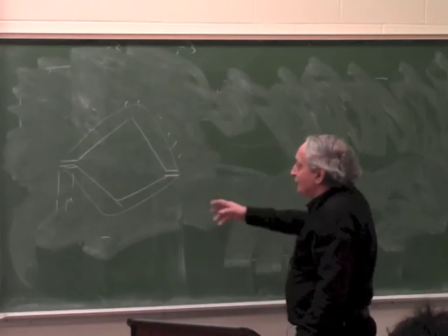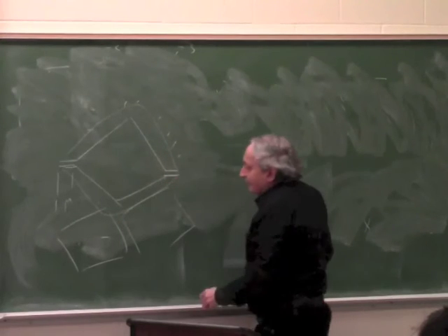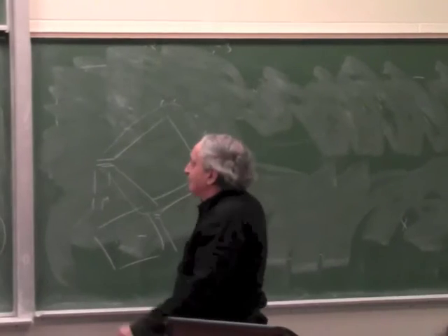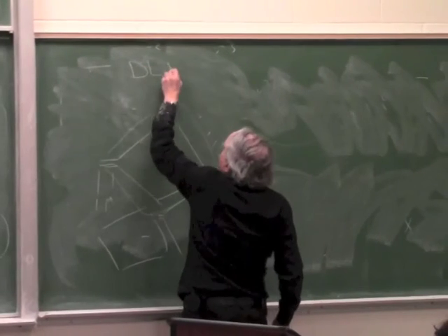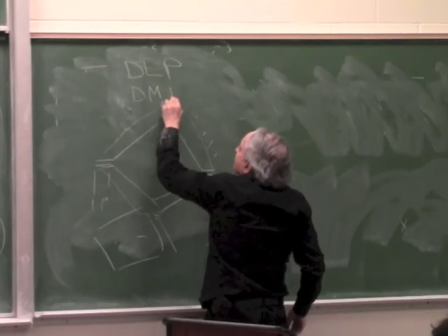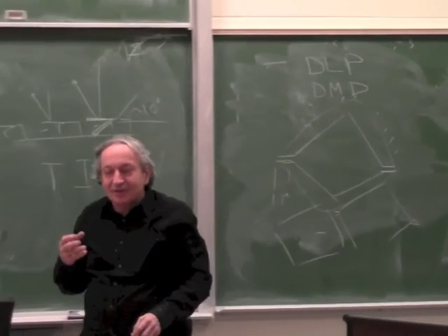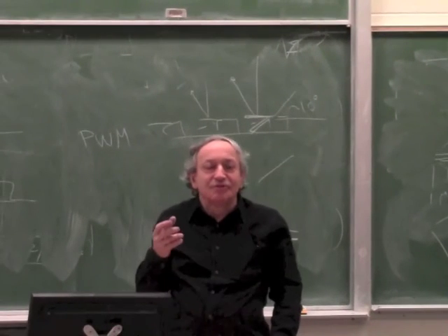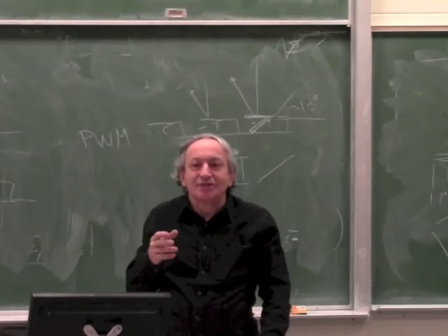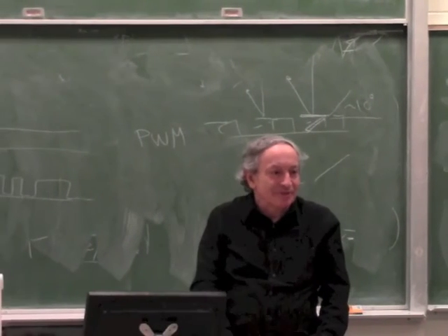So actually, if you look inside this chip, it's squares tilted at 45 degrees sitting on torsion hinges. There are some pictures on the internet you can see close up. Today it's called DLP, Digital Light Processing. Originally it was called DMD, and it's made by TI. It's quite a masterpiece of micro machining. I would say that's the most sophisticated micro machine part in the world, because it has not only the million mirrors, it has all the electronics to drive it, and a million other things all in the same chip.